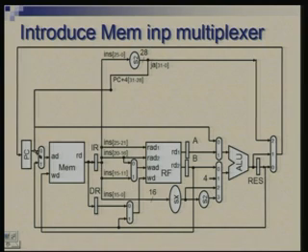So, for example, you can take paths going from one storage element to another storage element. When you are fetching an instruction, it is this path PC to IR, or there are paths from IR to A or IR to B, or from DR to register file write, and similarly the path from A and B through ALU to result register, and so on.